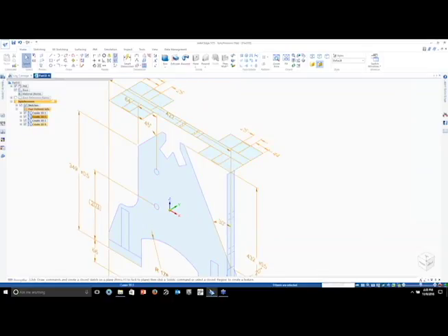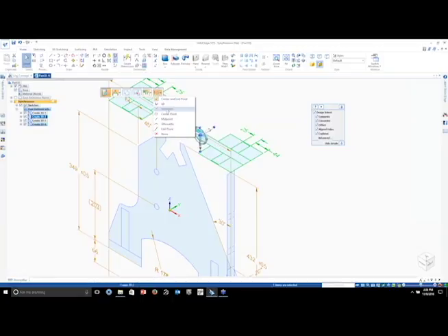Grab the center ball again, find a midpoint of one of the edges, and I can start moving it. So I can just find the midpoint of the next edge. Now that's lined up. All right, again, remember, you have to use the Pathfinder sketch to grab. If you're just trying to grab it from the screen, you don't get the steering wheel to move things with.